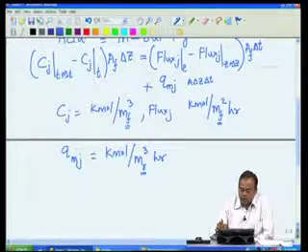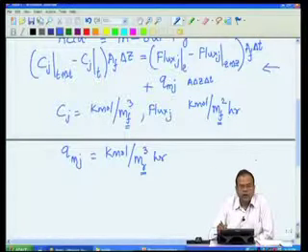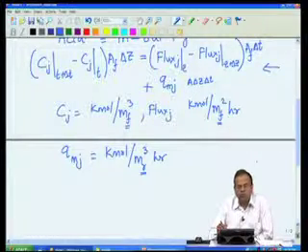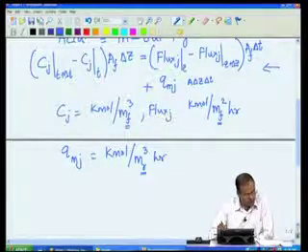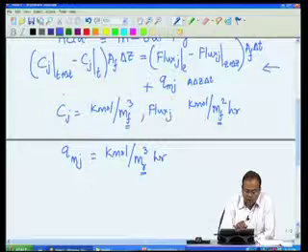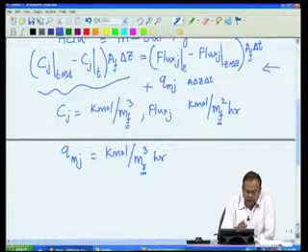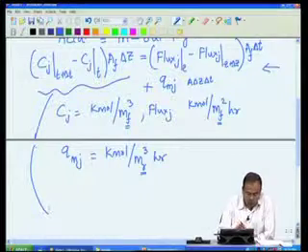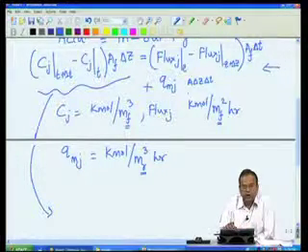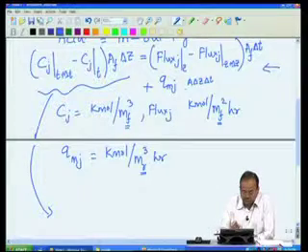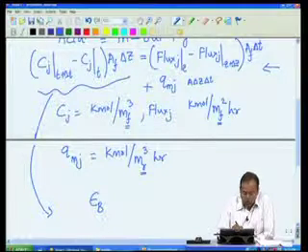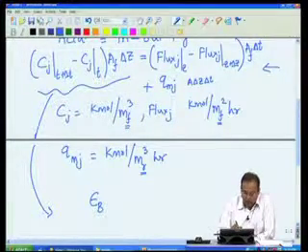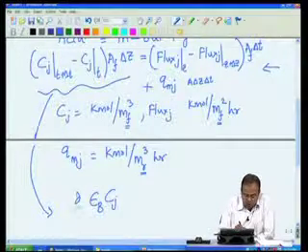So, now if I divide this by A delta Z delta t and take a limit as delta Z goes to 0, delta t goes to 0, that is convert a difference equation into a differential equation, we will get, for example, the first term over here, the accumulation term, will simplify to, remember we are dividing by A delta Z. So, AF by A, that is my epsilon bed, the fluid volume by the bed volume, epsilon B dou Cj by dou t.